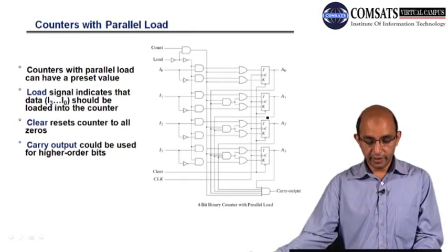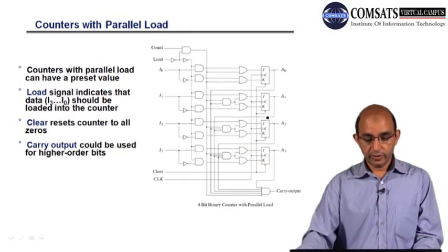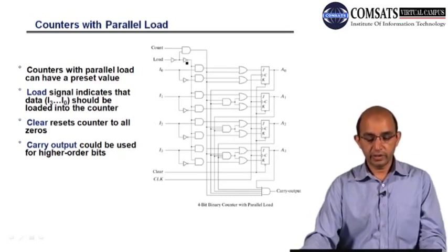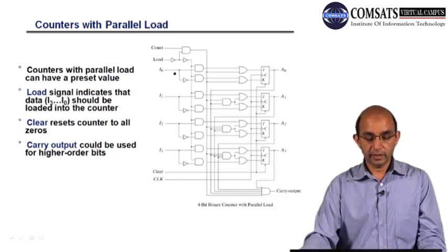And here we have added another control, that is the parallel load. You can see that we have a control named count, and then we have another control, that is the load. This control has been introduced because we want to load data onto the counter or onto the registers, or we want to store predefined data into those flip-flops.